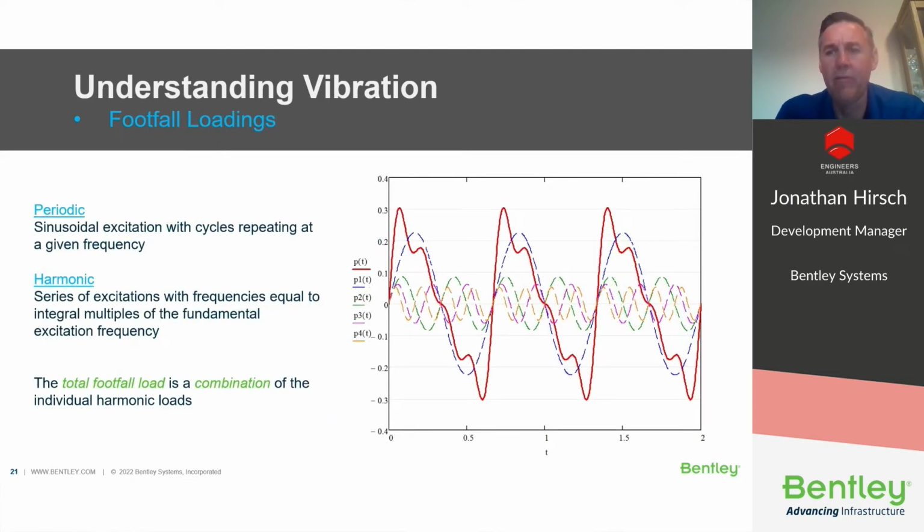So we need a way to quantify the dynamic loadings that we will use for footfall. The loading shown with the red curve is the design footfall shape used in the design guide and was developed using measurements of actual footsteps. This shape can be decomposed into 4 simple harmonic loads, which are the dashed lines in the graph, which are integral multiples of the fundamental excitation frequency. And decomposing into simple harmonic loads allows for solution of these simpler loadings using either a closed form solution or a modal analysis.